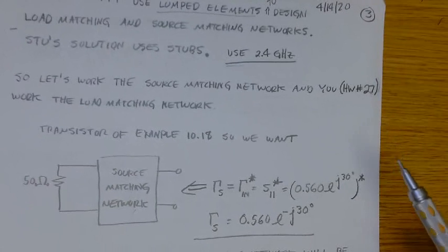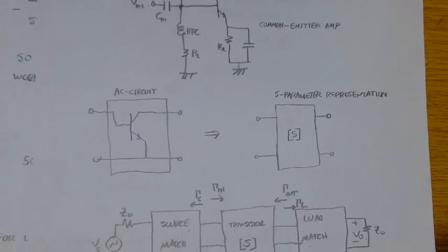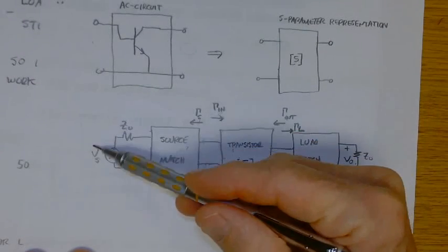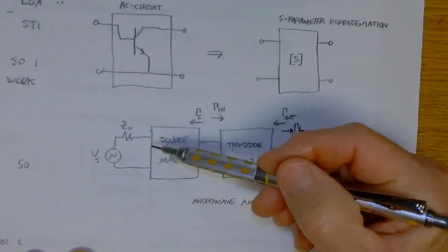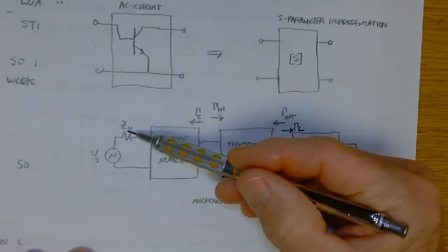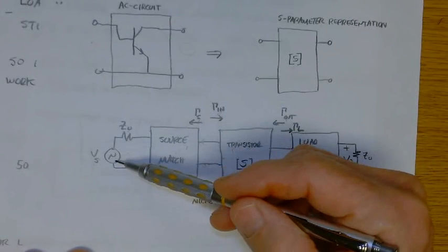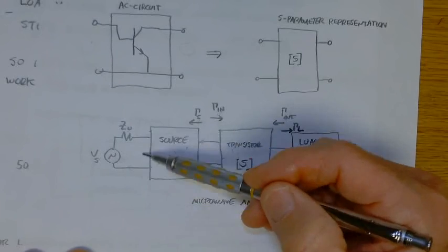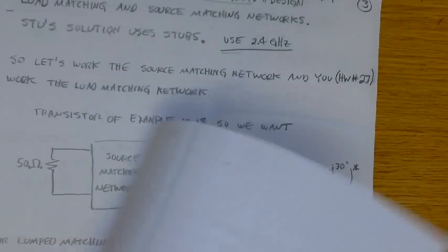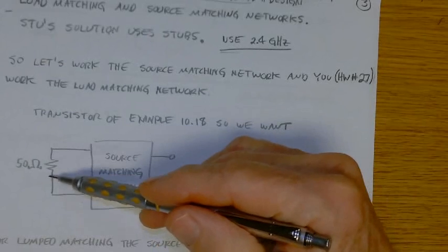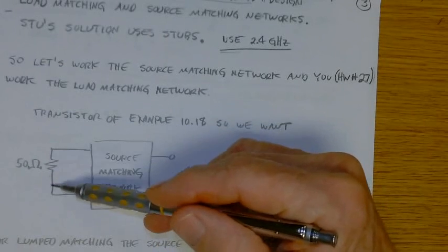Okay, remember, here's what we're up to. The Thevenin equivalent of this, the impedance seen looking back into the source, is just Z naught. How do you find what that is? Well, you short out the source, and that just puts Z naught across this pair of terminals. So Z naught in this case is a 50 ohm system.